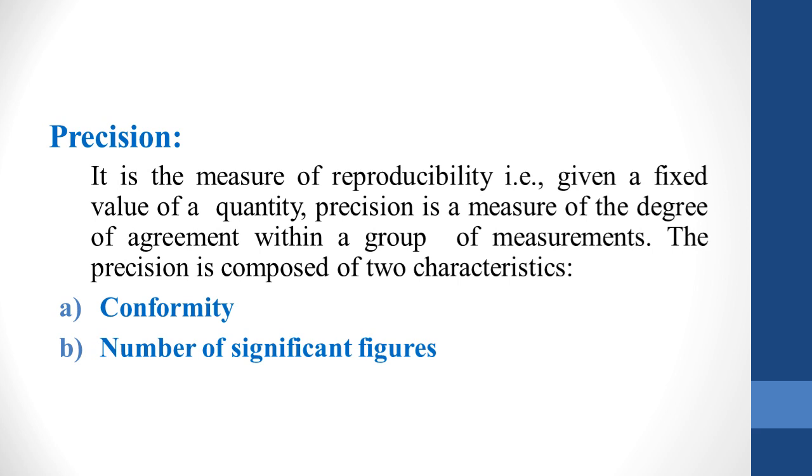Now, every time we take a reading, the ammeter is as precise as ever. We can take readings down to 1 by 100 of an ampere, and the readings are consistent and clearly defined. However, the readings taken with this ammeter are not accurate because they do not conform to truth on account of its faulty zero adjustment.